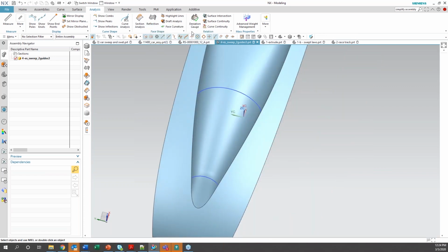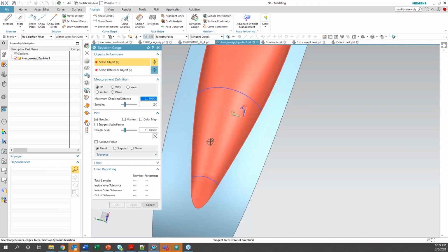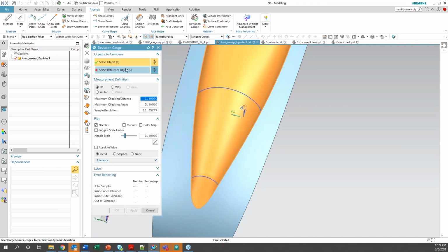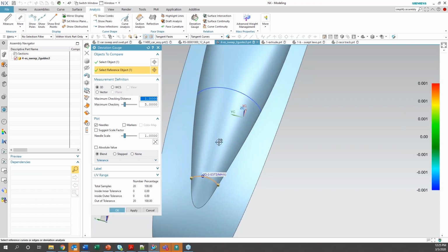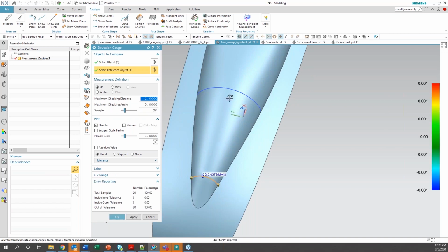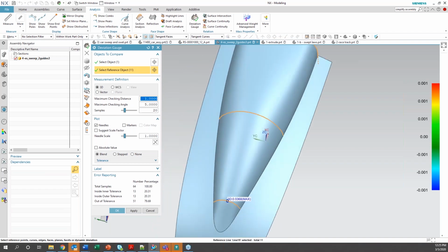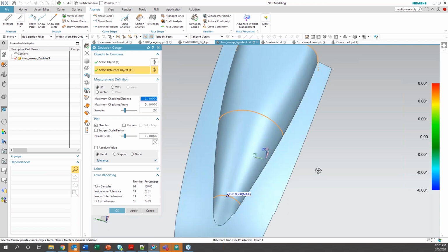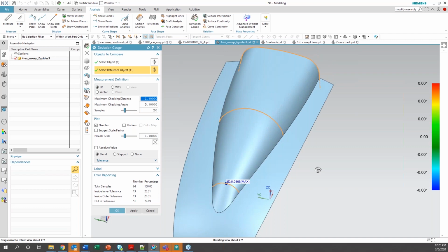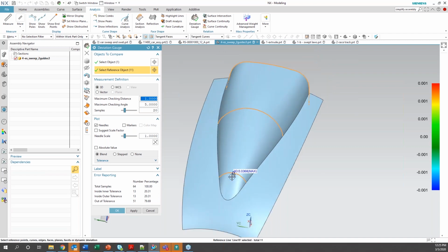If we do a deviation gauge between the surface and the underlying objects, like I was saying, we want to hug them if they were scientifically important curves, physically important to aerodynamics or thermodynamics. You're pretty close here. This is in millimeters, so we're at like 3 to 4 hundredths of a millimeter. It's probably less than 1 thou in inches.